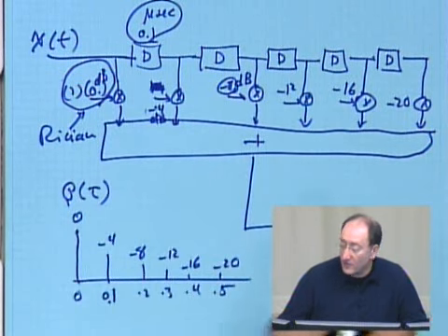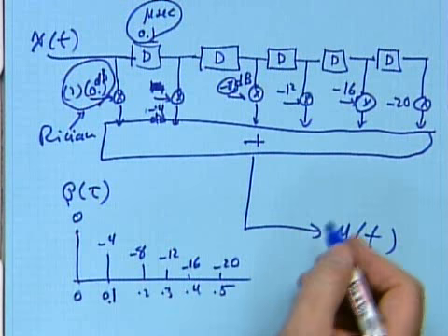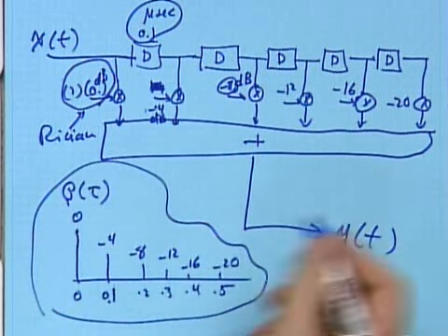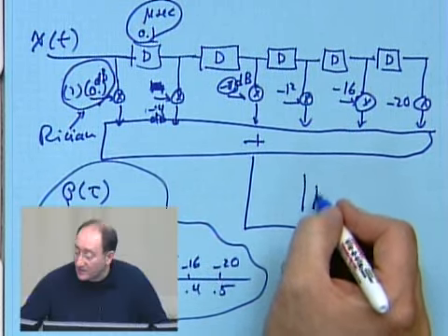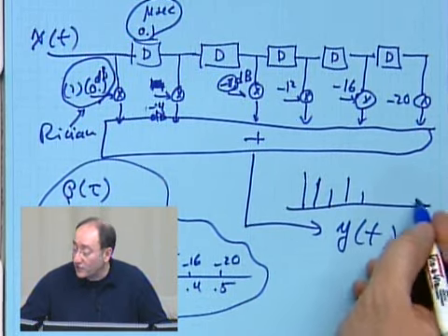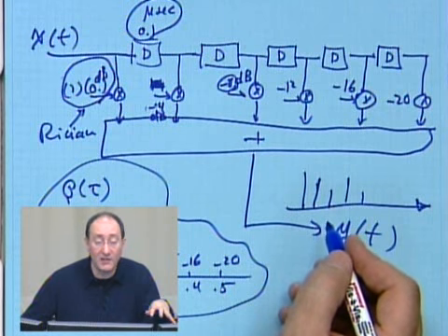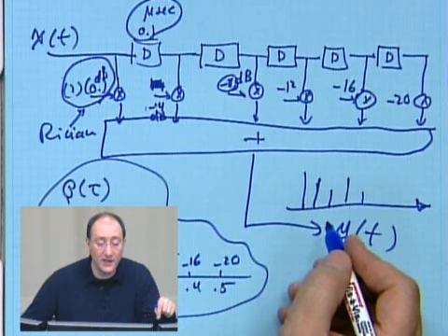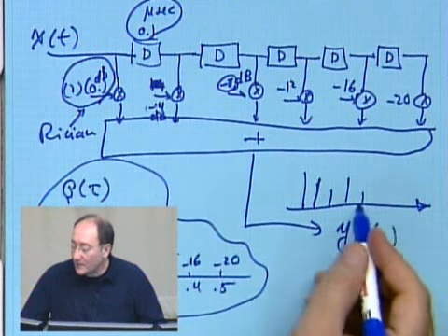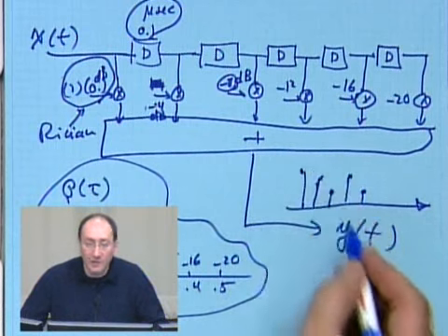And then the output in here is a channel impulse response. How does this channel impulse response look? If you sketch it, it's not like this thing. This is the average of this thing. If you sketch it, there are a bunch of these taps which are going up and down. If you look into the videos that I have, they show you some of these variations of the channel. Some simulations are in some of my labs. If you go to the website, I have the laboratory on real-time channel simulation. One of those laboratories shows you the variation, simulation after variation. So all these taps are going up and down all the time.